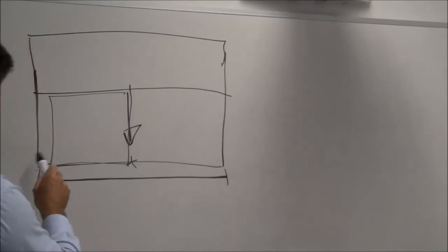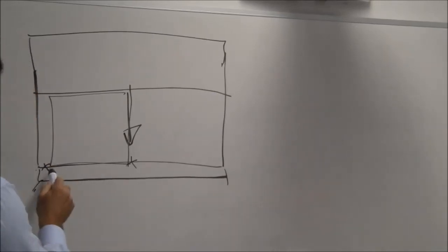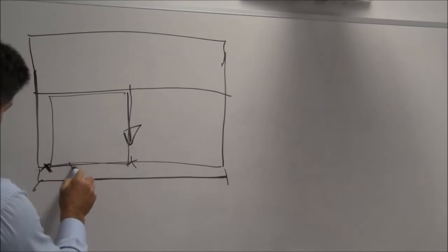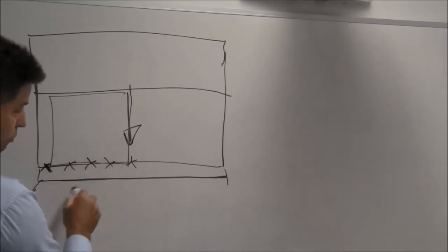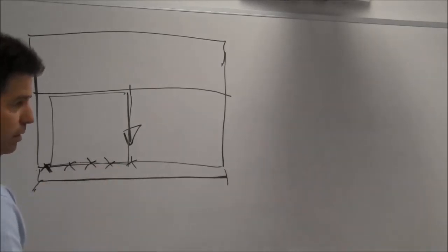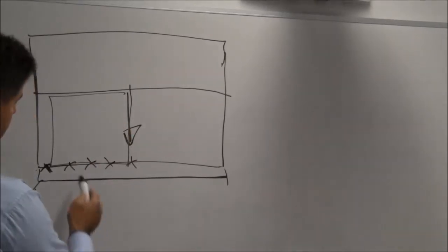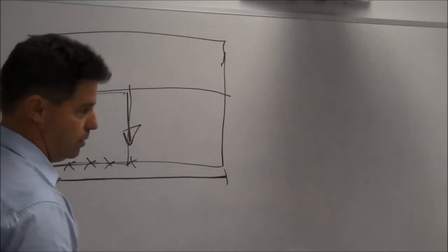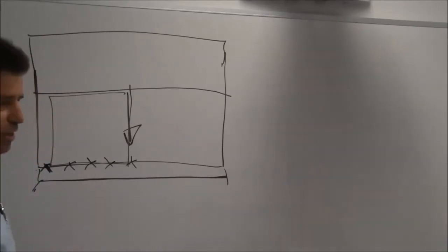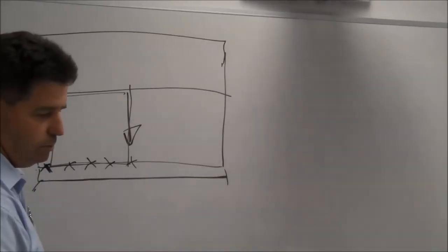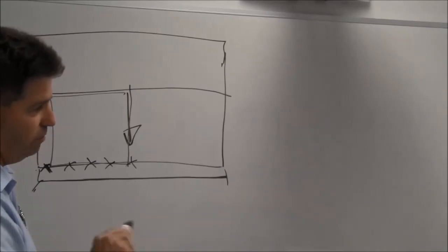So in our office, depending where we put the outlet, we'll nominate that roof area based on where the outlet's located. So obviously work on the worst case scenario for sizing, but that's something that is not quite the norm. It's different with eaves, I suppose, because they're probably flat, you don't have stop ends.